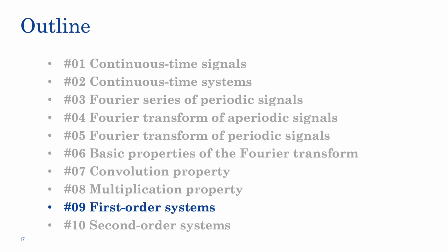So today we first learned how to represent the frequency response of a system in terms of its magnitude and phase, the so-called Bode plots. Then we focused on a first order system and studied the behavior of the impulse response, the step response, and the frequency response of such a system, both its magnitude and phase, and we learned how to represent it. In the next class, we will extend our study to systems of the second order.